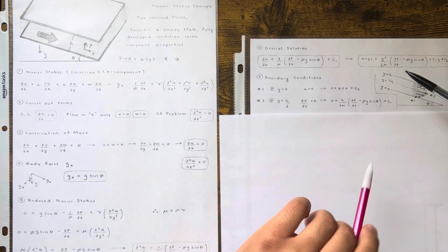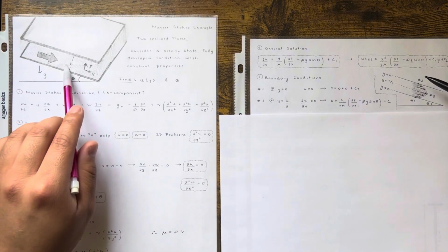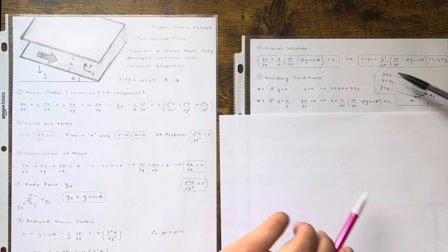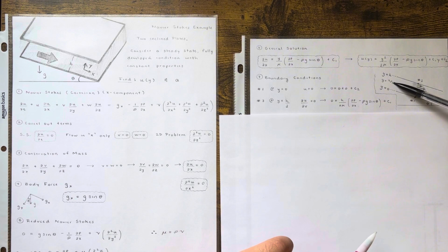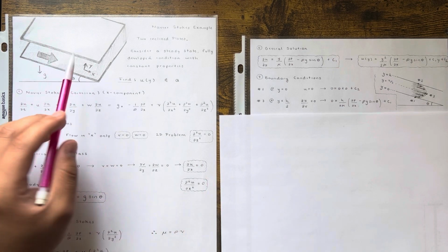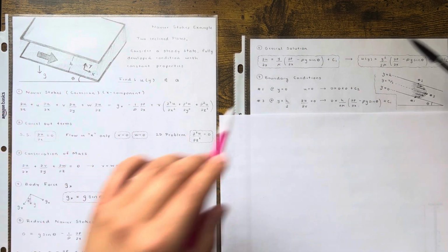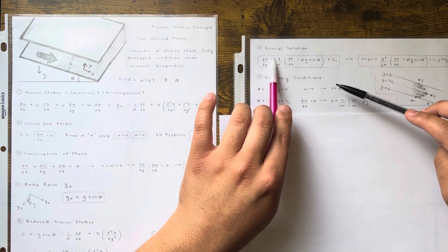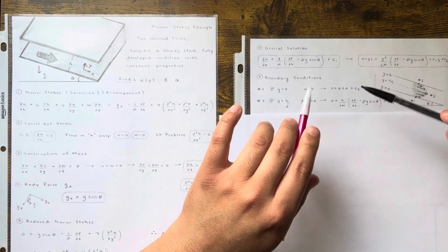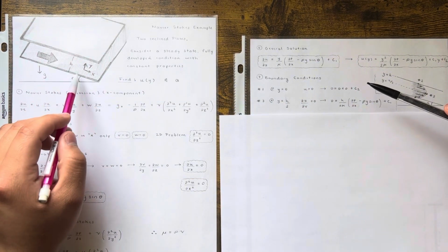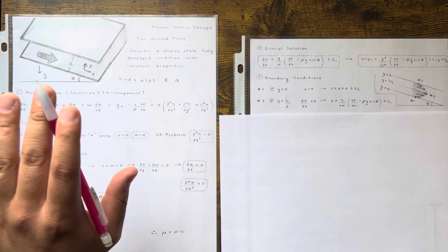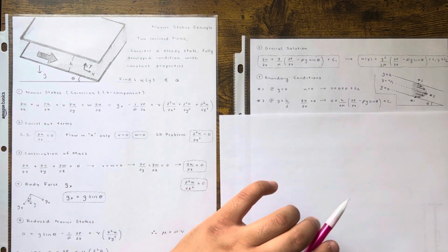And in this case, I chose my datum line because it goes from 0 to h. That's what the problem told us. So y is equal to 0, h over 2, and then h. You could have done y equal to 0 at the middle, and then h over 2 up top, h over 2 at the bottom. As crazy as it sounds, it wouldn't change your answers at the end. It would change your velocity profile, but at the end of the day, when you start plugging in any values for y, it shouldn't matter.